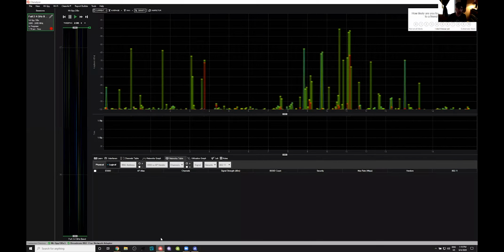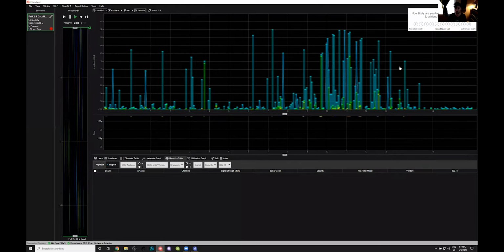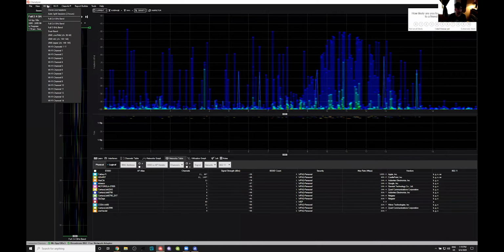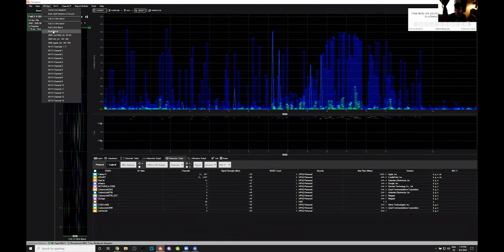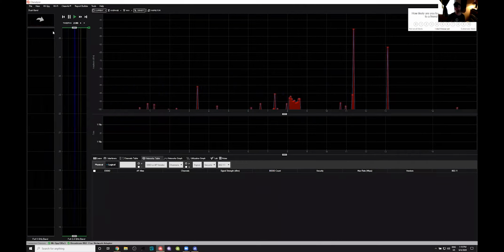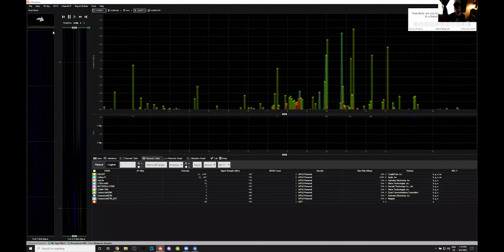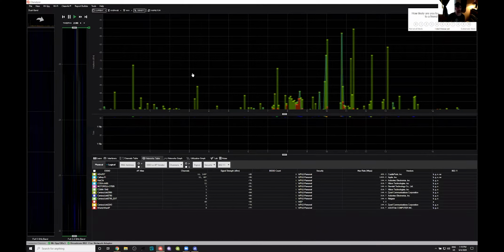So when you first open up Channelizer, it actually starts sweeping the 2.4 gigahertz band only. And so to remedy that, you go to Wi-Spy here at the top left and just select dual band if you want to see both the 2.4 and the 5 gigahertz band. So this will dedicate the resources of the Wi-Spy DBX to sweep both bands simultaneously. And so here we see the 2.4 gigahertz band. To toggle between the two, you just click the arrow in the top left corner over here.